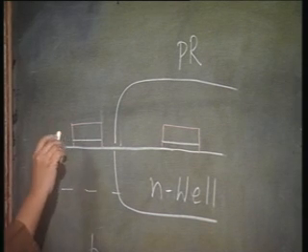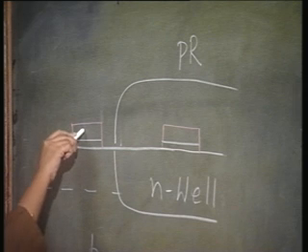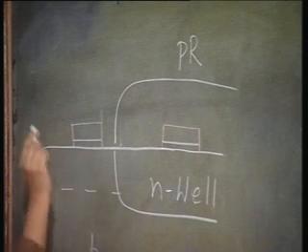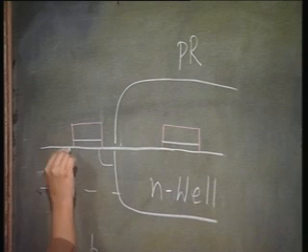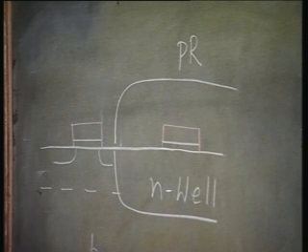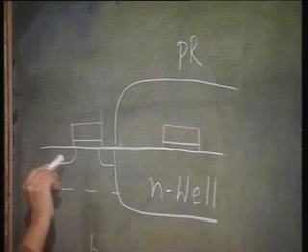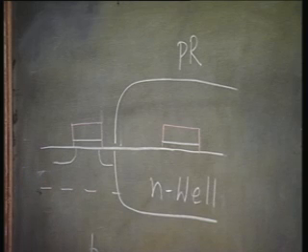Because you are doing it at low energy, this mask will mask the boron implantation. You will have just boron here and boron here. So, essentially what you are doing now is the channel stop implantation for the N channel MOSFET.